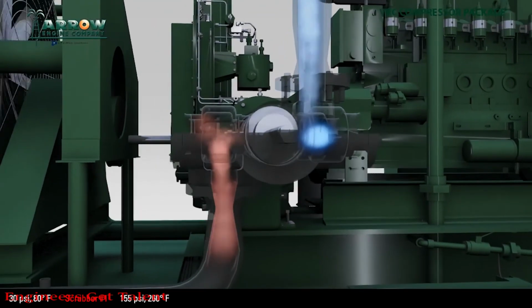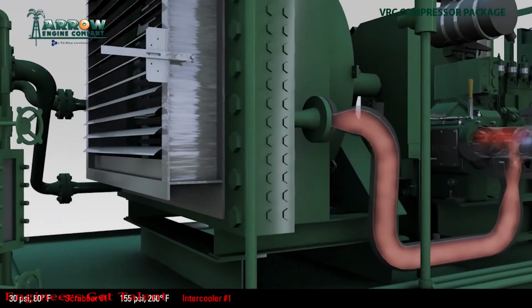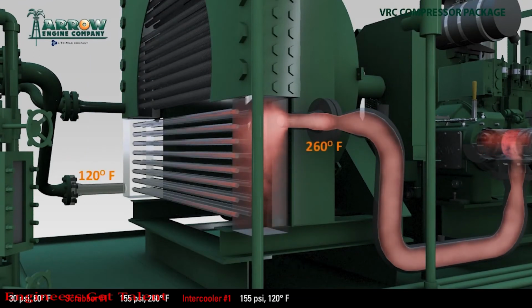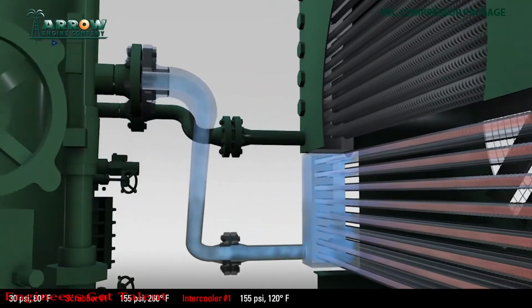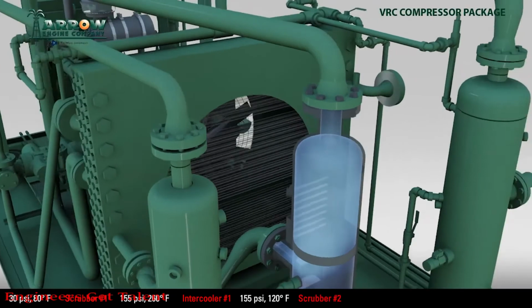As it exits the first stage, it goes into the intercooler. This cools the gas down to 120 degrees. The heating and cooling of gas along with the compression makes more liquids fall out of the gas. From here it enters into another scrubber so that the liquids can fall out.